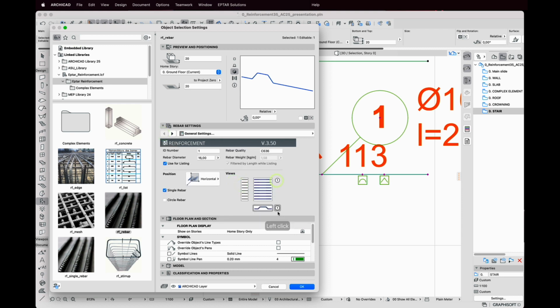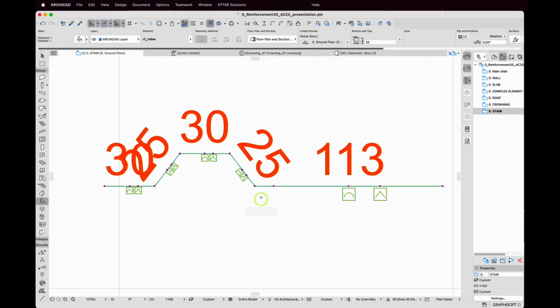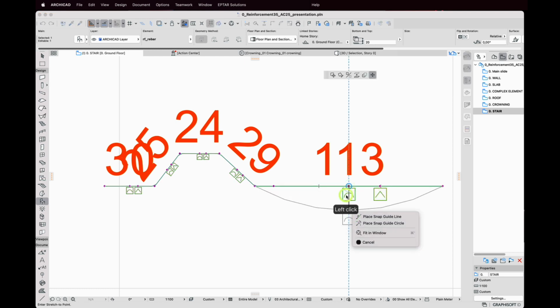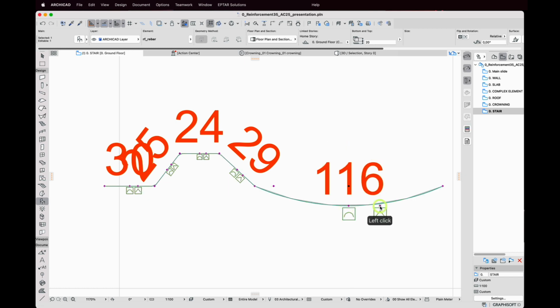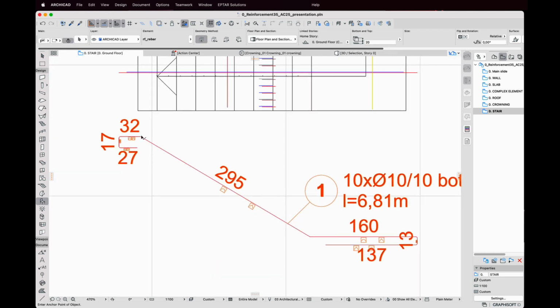Now I can change the shape of this rebar. I can make the straight part curved, or I can add new hotspots to this section. It shows that almost any shape is possible to create. I did the same modification of the rebar, I just adjusted points of it to the stair geometry.